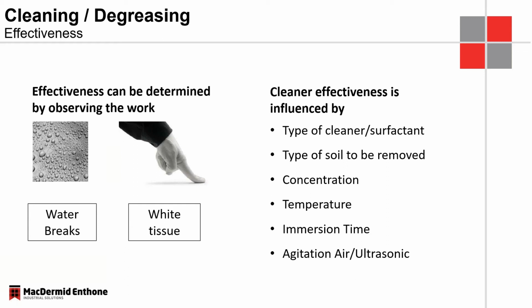Any sort of movement, any sort of exchange of the solution on the part, on the component, will actually help removing these solids, oils, greases, so on and so forth. Ultrasonic, on probably everyone's wish list, very effective removing polishing compounds or any sort of other residue on the surface.